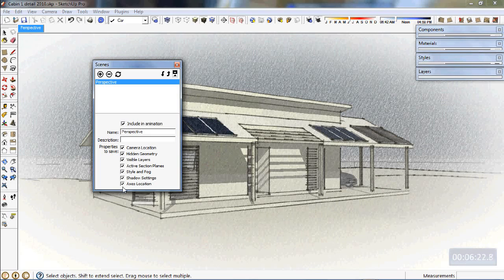Then I'm going to add some more views. So I'll add another scene. This one I'll come down into the name and change that to Floor Plan. Okay, and press Enter, and then I'll update that. I'll do a north elevation. I'm just picking some views as examples. Oops, what have we done here? We could change name. North elevation. Press Enter. And I'll do also a west elevation, and then I'll do a section. So that'll be the views that I'll set up.